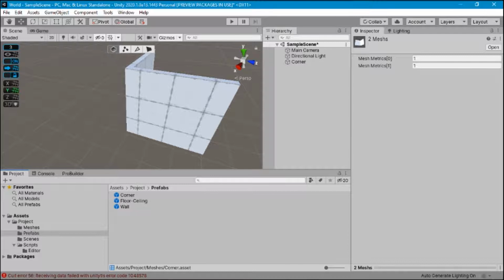Some walls may fully surround a perimeter, in which case, we can also remove the faces on the connecting sides. However, if our wall is going to leave part of the perimeter open, we'll probably need a couple of tiles with their connecting sides untouched. We must also consider some parts of our scene might be seen from only one side. There's no use in having two-sided walls if all the action is going to happen in just one side. A similar reasoning can be applied to floors and ceilings.